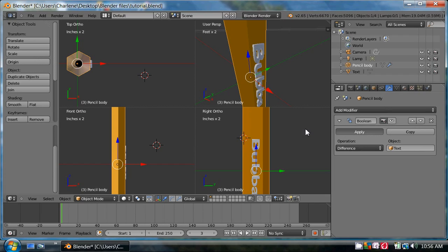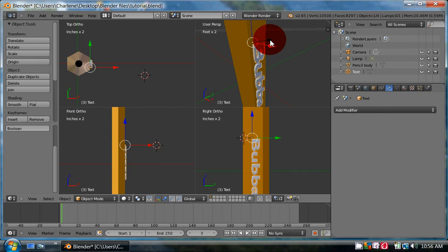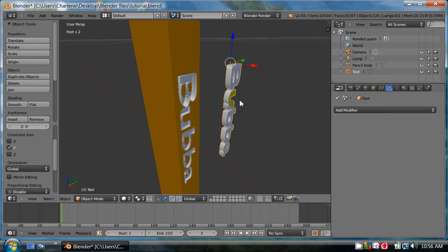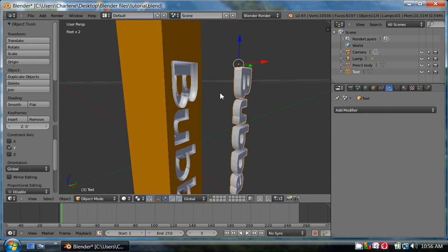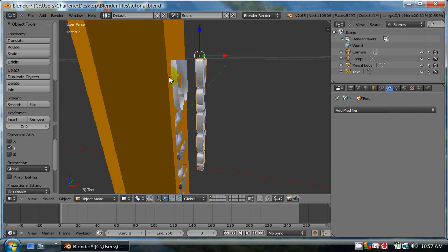And we're waiting, waiting, waiting. All right. All the stuff went away here, so let's drag the drill tool out of the way, see how we did. Very nice. Okay. So let's take a good close look at this, Control Alt Q. See how clean our drill was. Not bad. It looks like it left part of the B sticking out of the top. So to fix that, we're just going to have to select those faces and get rid of them.